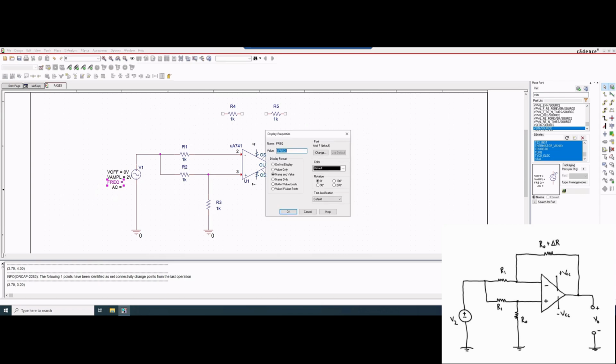And same thing with the frequency, it's going to be 500 hertz. So we'll just write in 500 hertz, and then we're going to leave the AC blank. Now this resistor right here we want to change to be 1.95 kilo ohms, so we'll just do 1.95. And then for this one right here, it's going to be 1.95 kilo ohms as well, because these are actually the same exact resistors. So they're measured the exact same, but we do have to have different labels for them.